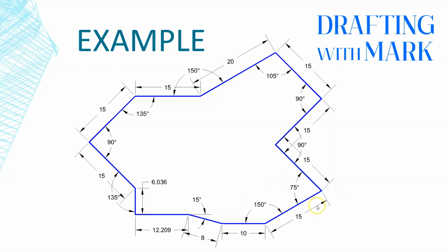We can swing back and go this direction, 150 degrees, or if we know that this line has to be at 180 degrees, I'll sketch this out for you. And once again, please don't be too hard on me for my crooked lines here. But I know that this has to be 30 degrees, so this angle on this side is 30 degrees. That's 150 because if it's a complete straight line, it has to equal 180 degrees. So that's going to help us a lot instead of counting all the way back this direction and typing in 150 or clicking until we get to 150.